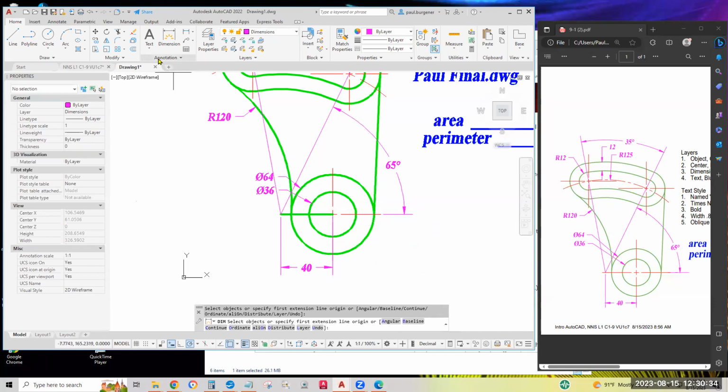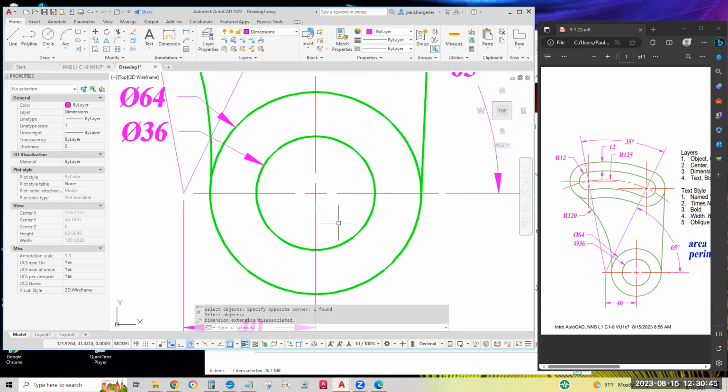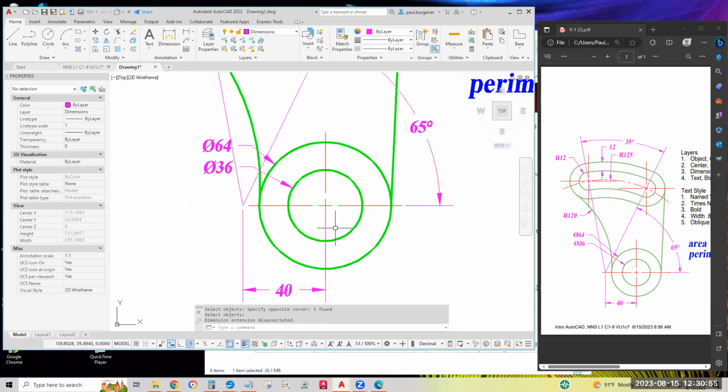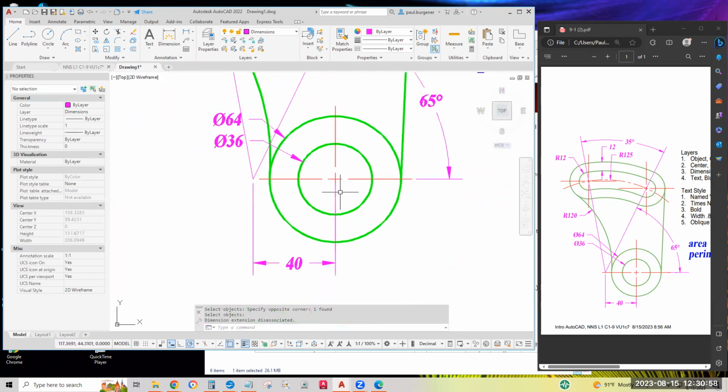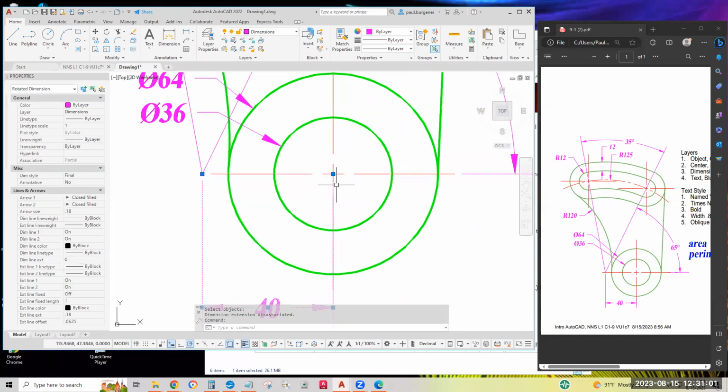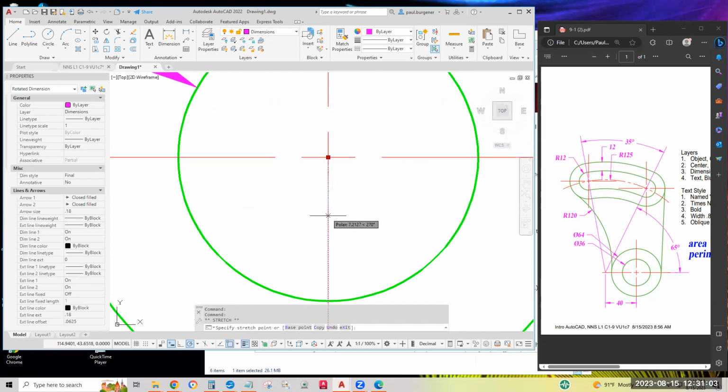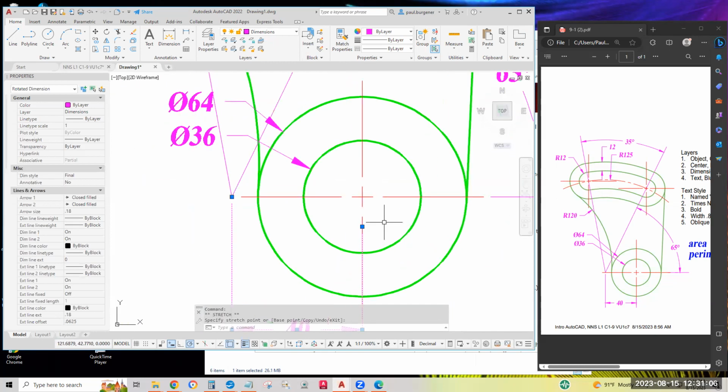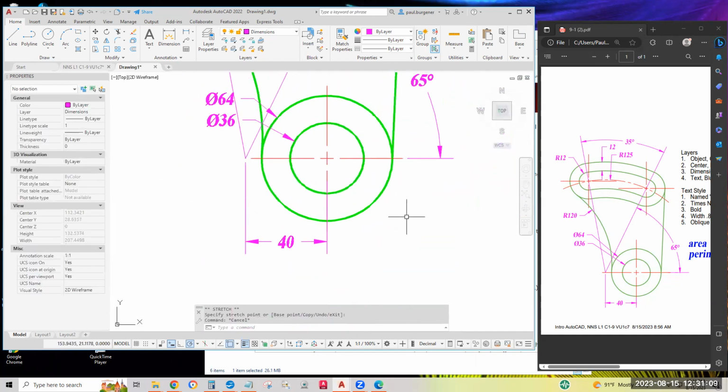Let's erase that green again. Regular window that only selects what it completely encloses. Ah, check it out. You got a magenta line there. We could put a wipeout. A wipeout is a cloak of invisibility and then turn off its frame. But I think I can select this and slide that grip down into the red area here. And that way it restores that space.